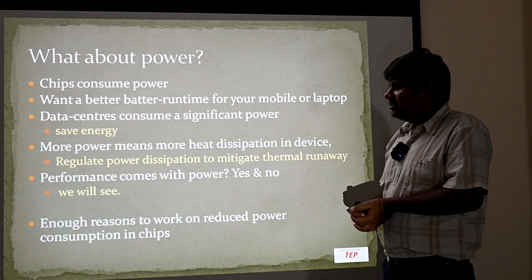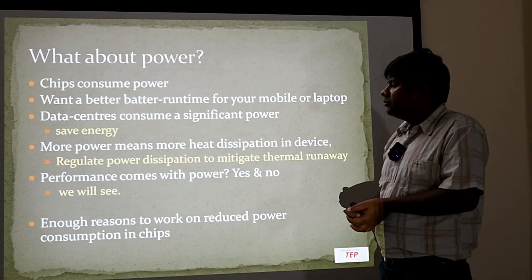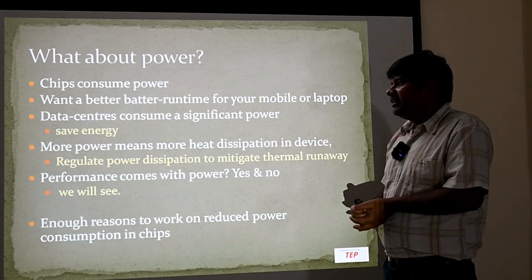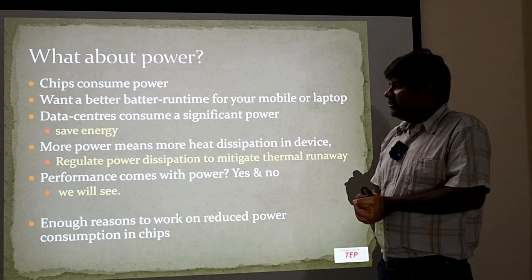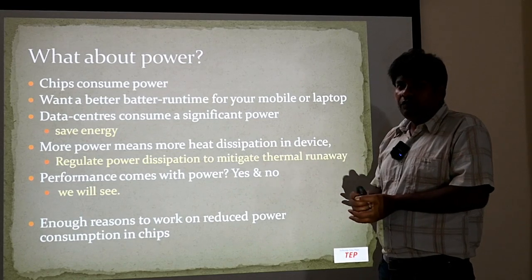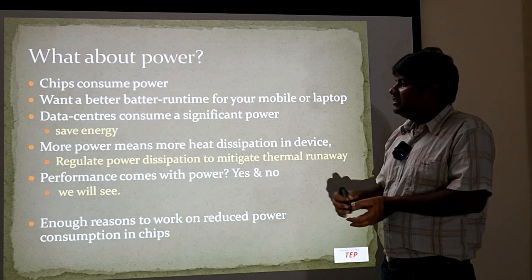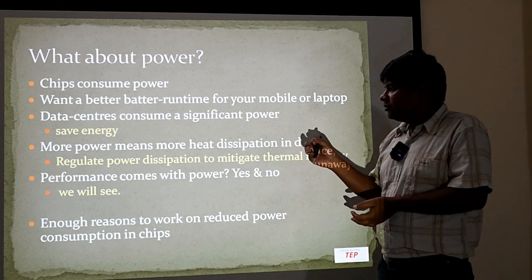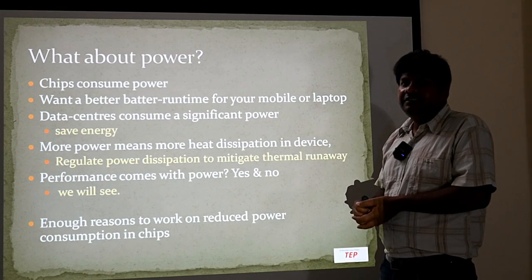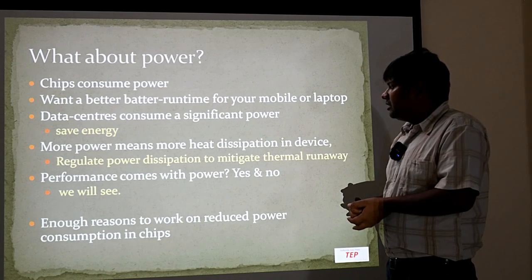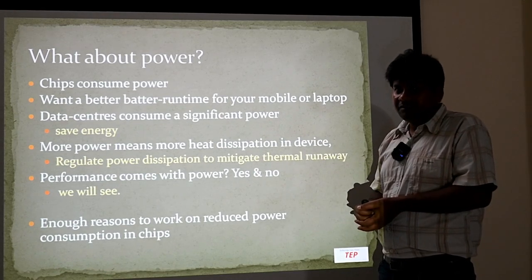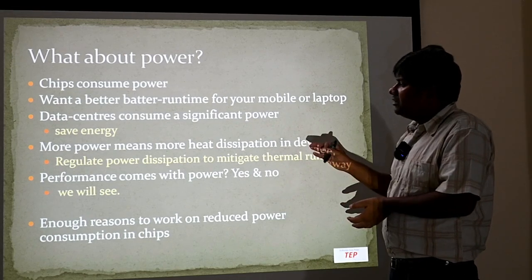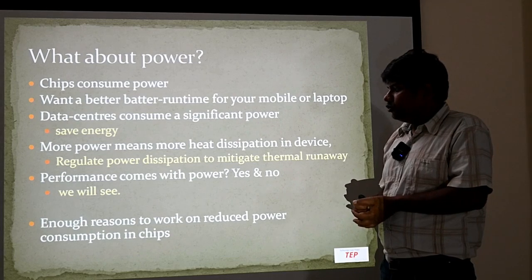We save the energy, we save our fossil fuel, also we save our environment. So that's the motivation of saving the energy. Third motivation is that even if, suppose there is infinite energy available, there is a physical limit in the form of thermal dissipation, because the more power the SOC is dissipating, the more thermal heat is generated, and the high thermal dissipation will lead to higher temperatures, and that higher temperature can break your device, breakdown can happen. So that is also one of the motivations to keep the power dissipation low.